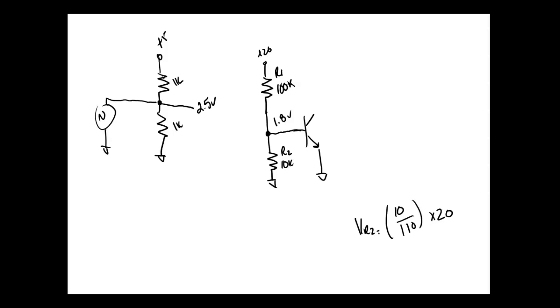What I want to do is come up here and bring an AC signal into here. When this goes up, the transistor turns on more, which would cause the output to go down. And when it goes up, I want it to do this. I'm going to try to bring a very small AC signal directly into the base and let it either add to the bias or subtract from the bias.